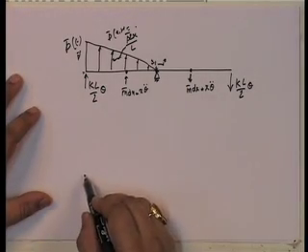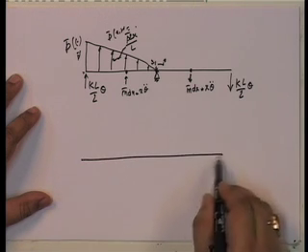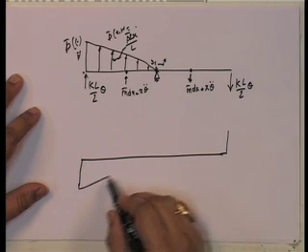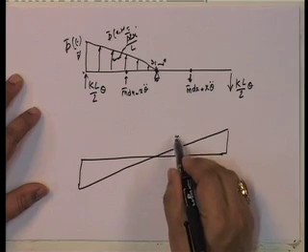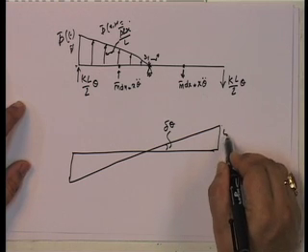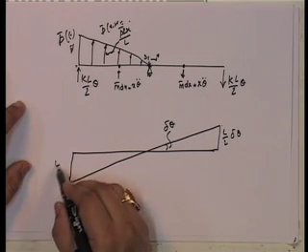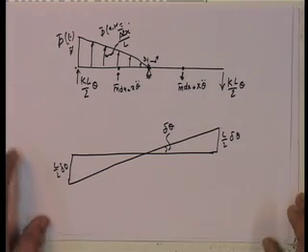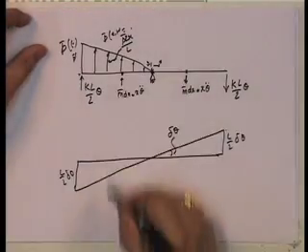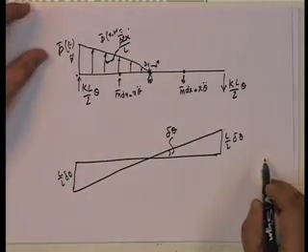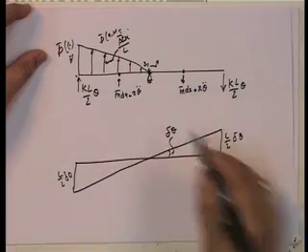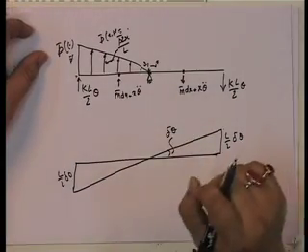Now I need to just put down the virtual displacement, which is del theta. I know that this is L by 2 delta theta, this is L by 2 delta theta. This is the work done by all the forces. Note that these forces will do negative work, these forces will also do negative work, so every term is negative.